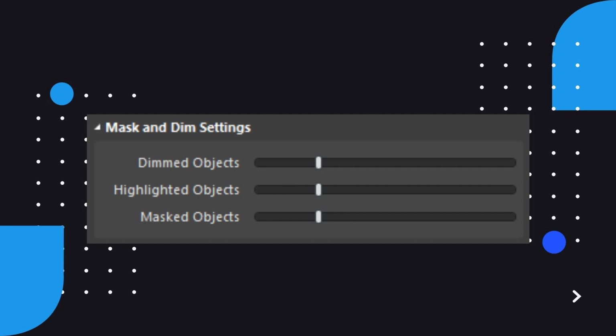Note that at the top of the PCB Rules and Violations panel, there is a drop-down, which can be used to select normal, dim, or mask. Dim and mask are display filter modes, where everything other than the objects of interest is faded, leaving only the chosen objects at normal display strength. The dim mode applies the filter but still allows all design space objects to be edited. The mask mode filters out all other design space objects, only allowing the unfiltered objects to be edited.